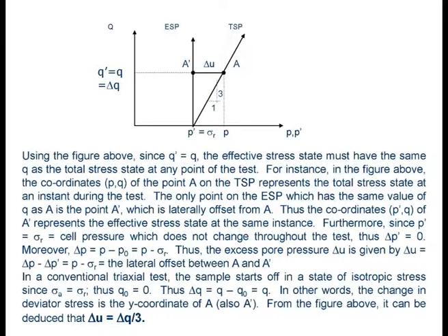You don't need to know anything about the total stress path. Whatever the total stress path is, the effective stress path will be a vertical straight line for an elastic material. Alright. So if you have a quiz and they say, please draw the effective stress path for this elastic material subjected to this total stress path, you don't even have to think: one straight line.